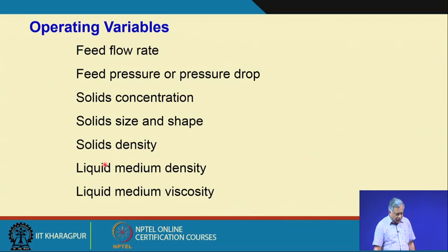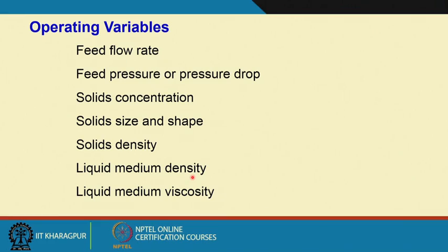then liquid medium density. Even the water, when you use, many times we use recycled water. So, recycled water may have some suspended solids. So, that liquid medium density also may be different from the density of your water. Then naturally, when you have a liquid medium density more than your water density, that means you have got some suspended fine particles, and naturally your liquid medium viscosity will also start playing a role. And even your liquid medium density and viscosity depend on the temperature.